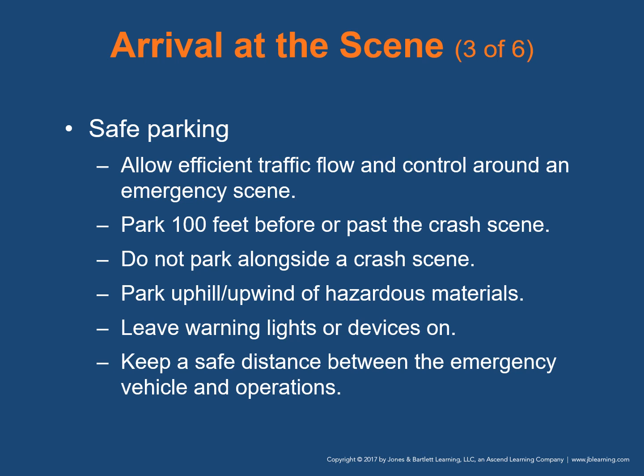As far as safe parking is concerned, pick a position that will allow for efficient traffic control and flow around an emergency scene. The first vehicle to arrive should park 100 feet before or past a crash scene to create a barrier between EMTs and traffic. Do not park alongside a scene. You may block the movement of other emergency vehicles. Park uphill and or upwind of a scene with smoke or potentially hazardous materials. And leave your warning lights or devices on. Keep a safe distance between your vehicle and operations at the scene.